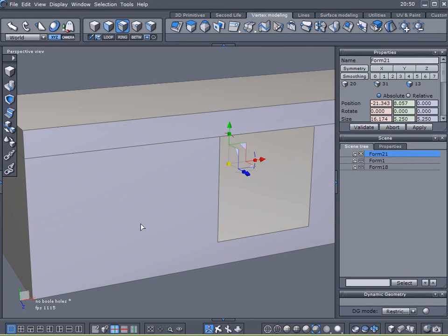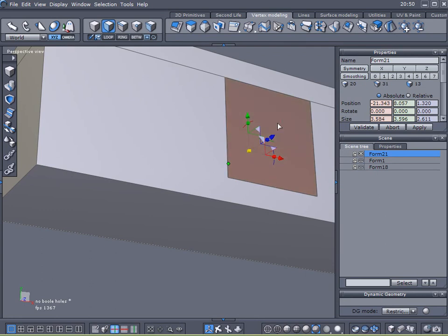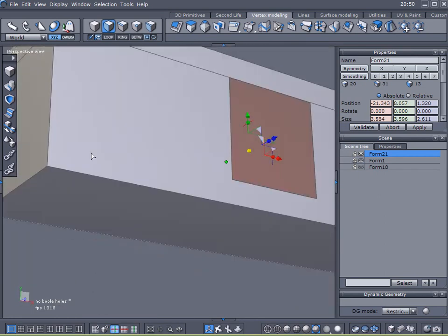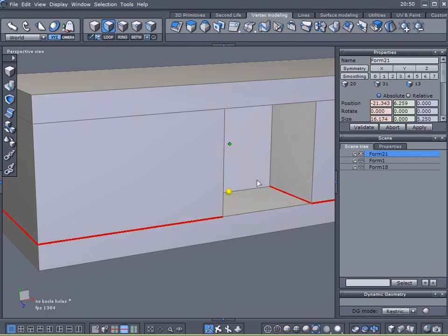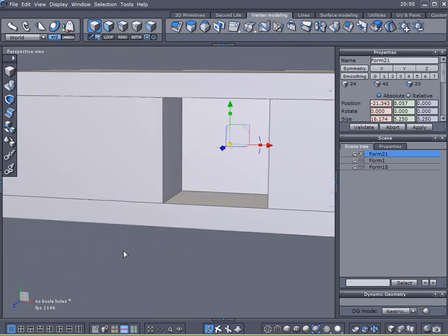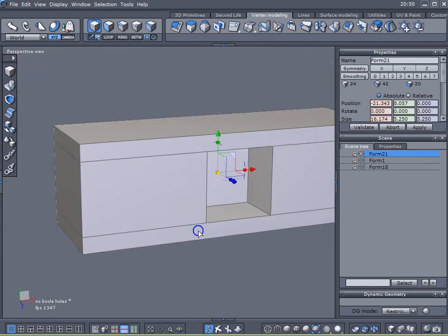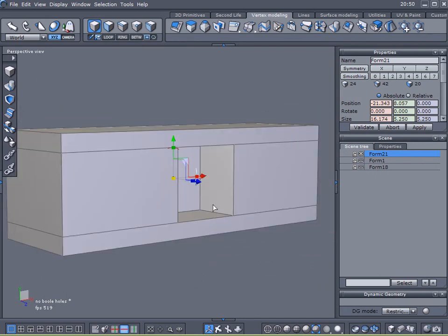Oh, well, it worked there, but notice something's amiss here. It created a solid object. It got all funky. So you can practice getting rid of some of the extra vertices, but you will need to leave some behind in order for it to accurately construct or maintain the integrity of the object that you have created.